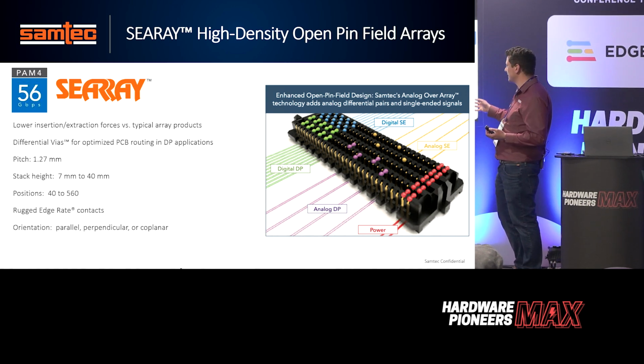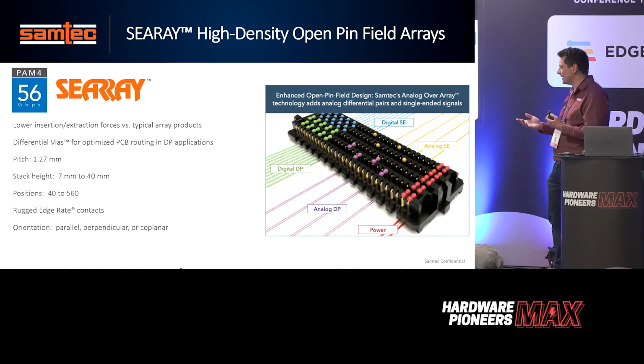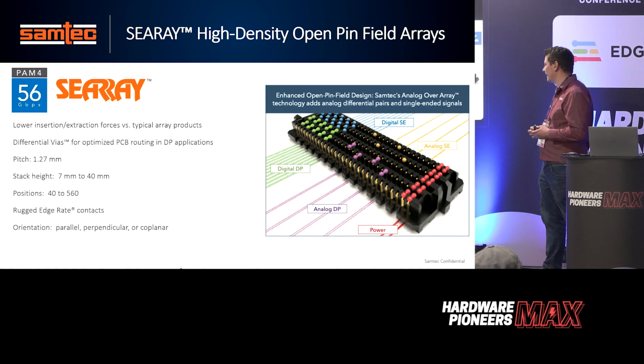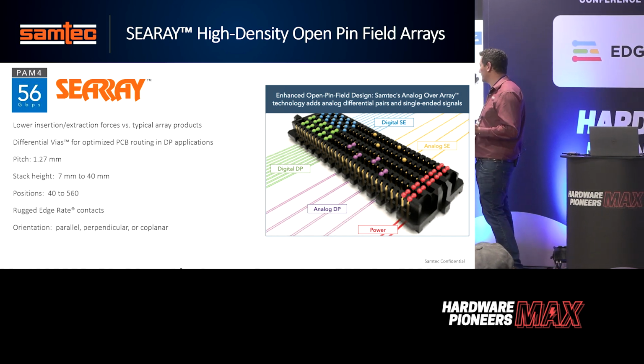So the reflections inside the connectors, we cannot change them. We can maybe change the capacitance around the connector, and it will change the performance of these parameters. But there's a certain level of things that you can do around the connector itself. So now we can get up to 8 gigahertz of RF signaling, differential pair, especially for RF SOC.